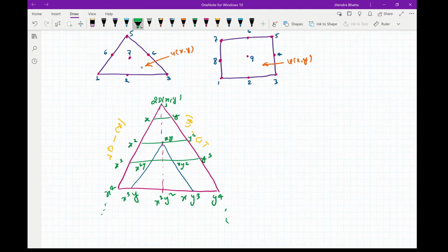If you want to choose a polynomial in 1D as a function of x, you can see here that for an axial member you'll only choose this part here as a function of x. So you'll have 2 terms for a bar element, which will be a0 plus a1x.